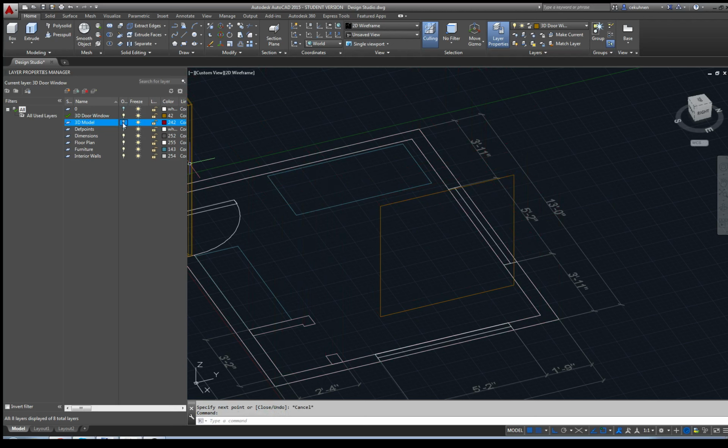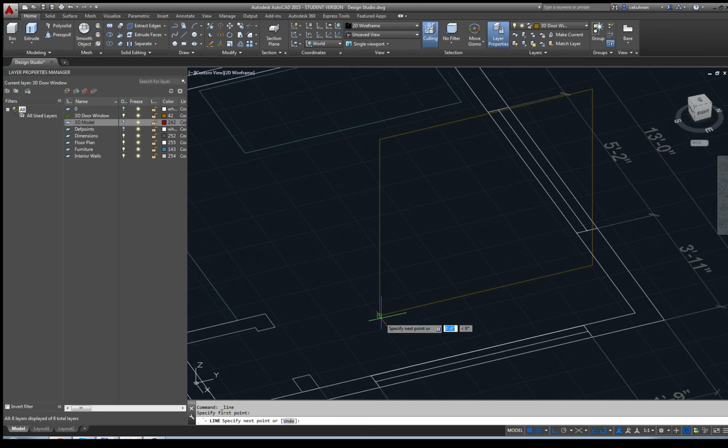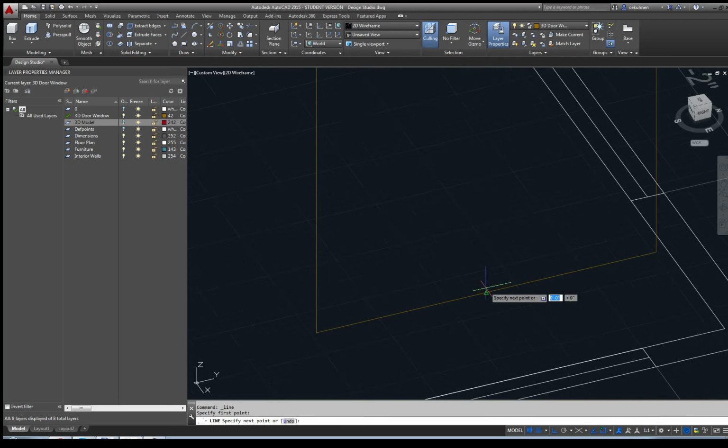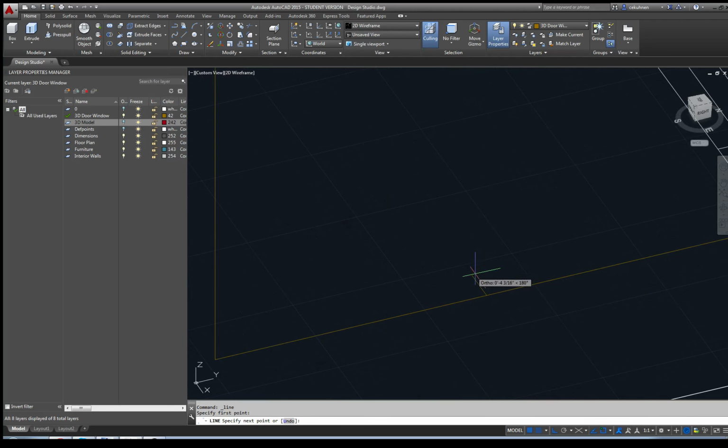Now, in this case, actually, I show you a different approach. So, for example, take a look at this. Let's say the whole thing should be maybe... actually, I go to the midpoint. This is important. So, midpoint, endpoint is turned off. So I go to this midpoint, and for example, I draw a line maybe 4 inches.